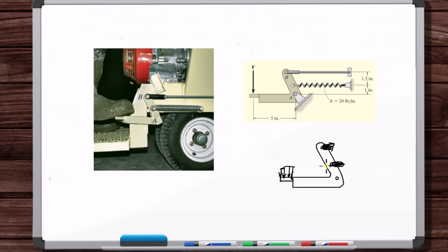If you went to all this detail, you solve for the unknown forces in the pin. I don't think we know the force from the foot actually either. So you solve for the force in the foot and the pin. And then you came back and did it with just point loads. The result you get for the forces in the pin, you won't notice any difference either way. Okay, once you work more statics problems, you'll get a feel for when it would be necessary to put a distributed load or not. If you had some large body acting over this entire span of the link here, then yeah, you're going to need to put a distributed load and analyze it that way.